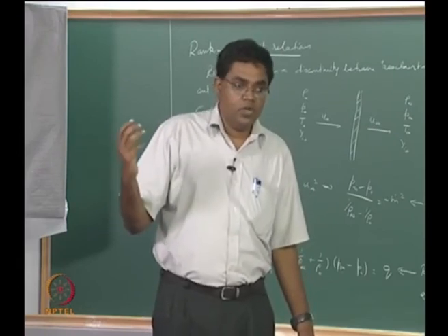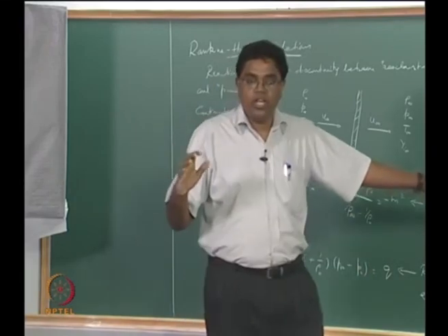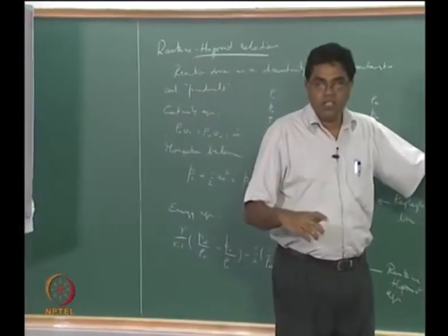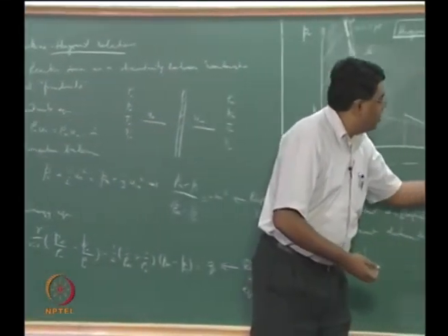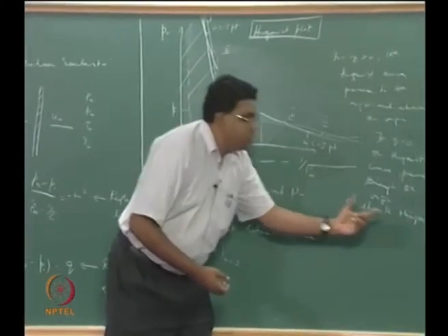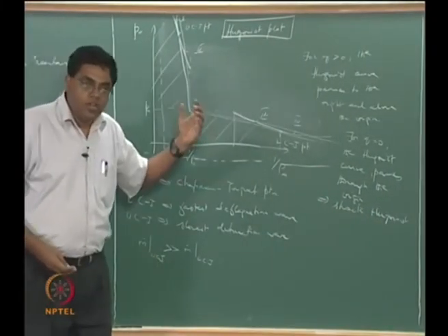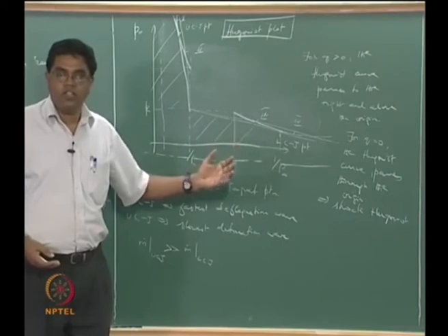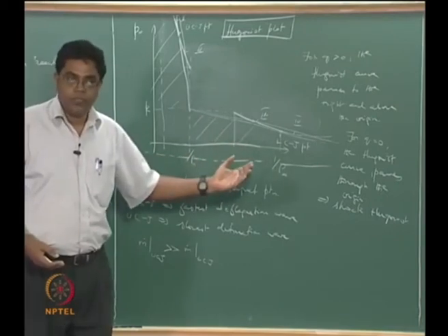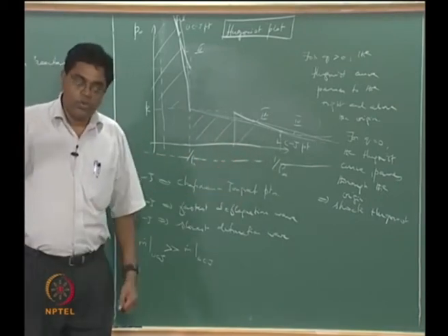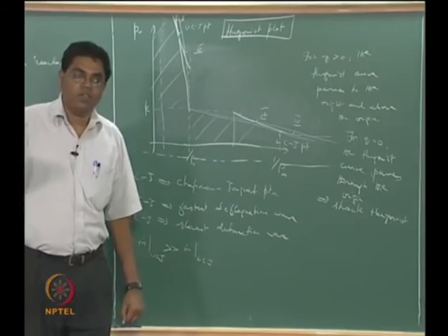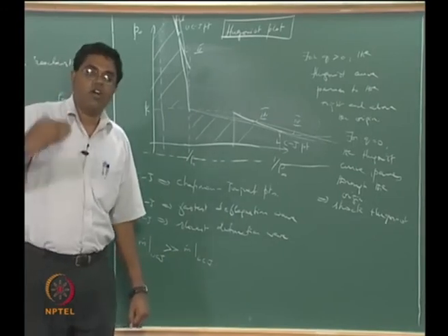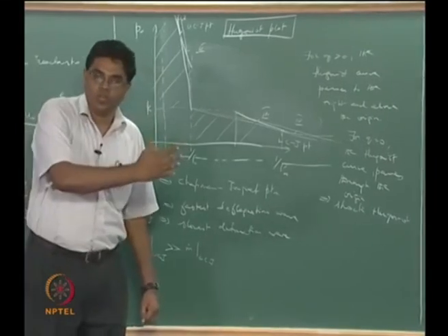Okay, and we will never do that actually, except to state that this part of the wave, that is the strong deflagration, is not possible if you now start taking second law into account, and that's the reason why you will never really find a wave starting from subsonic flows going through a strong deflagration to accelerate all the way to supersonic speeds.